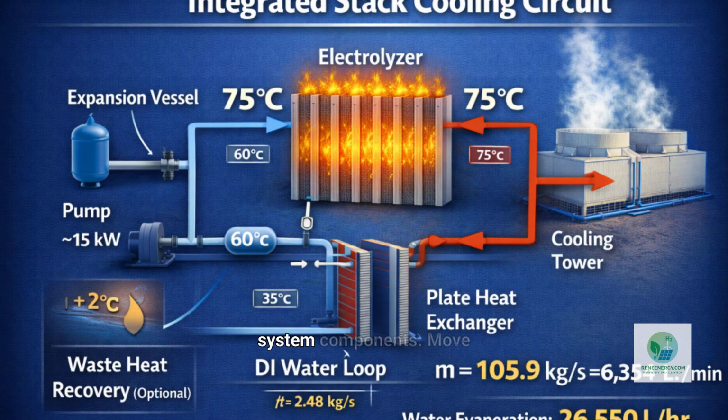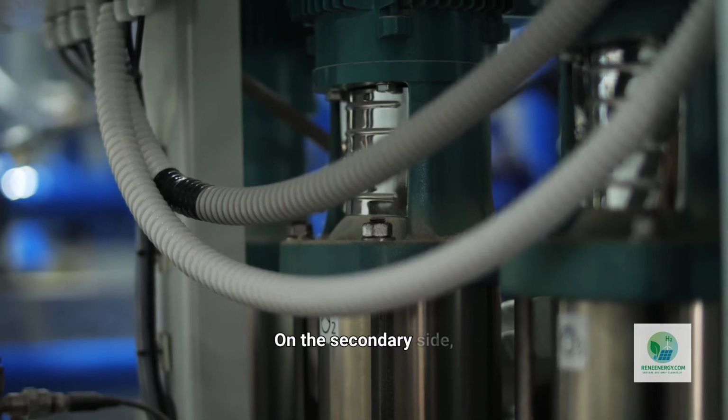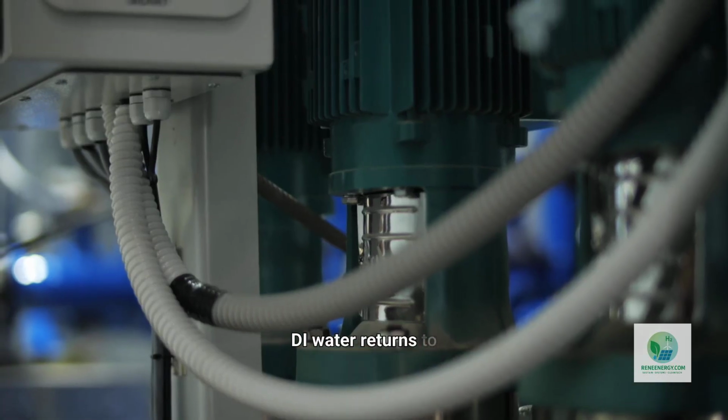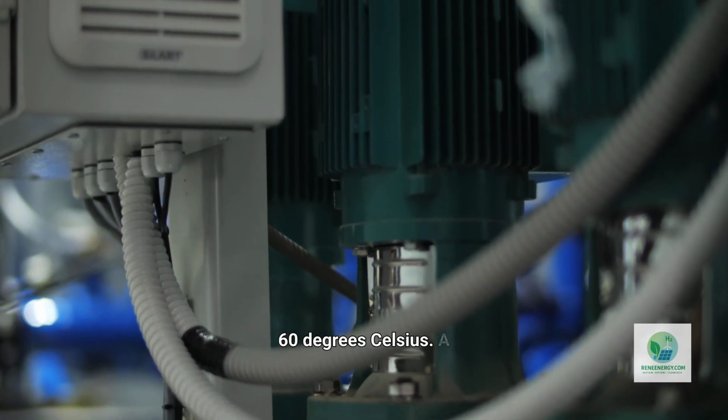Now let's integrate the system components. Move to image number 7. Image number 7 shows the full electrolyzer cooling circuit. Deionized water circulates through the stack in a closed loop. The hot coolant exits the stack at around 75 degrees Celsius. It flows into a plate heat exchanger. On the secondary side, cooling tower water absorbs the heat. The cooled DI water returns to the stack at approximately 60 degrees Celsius.